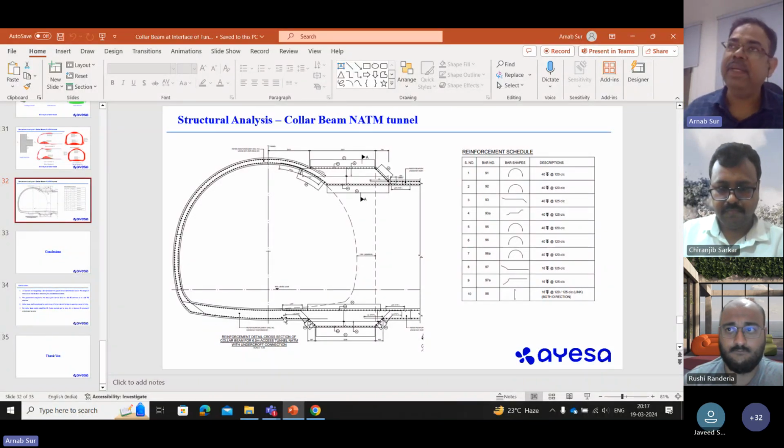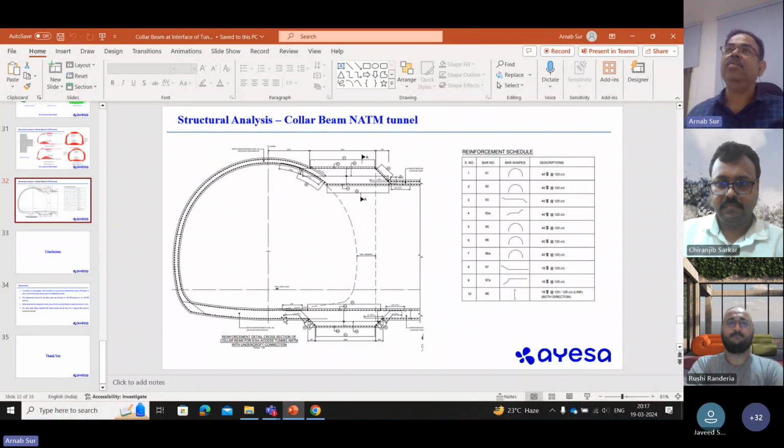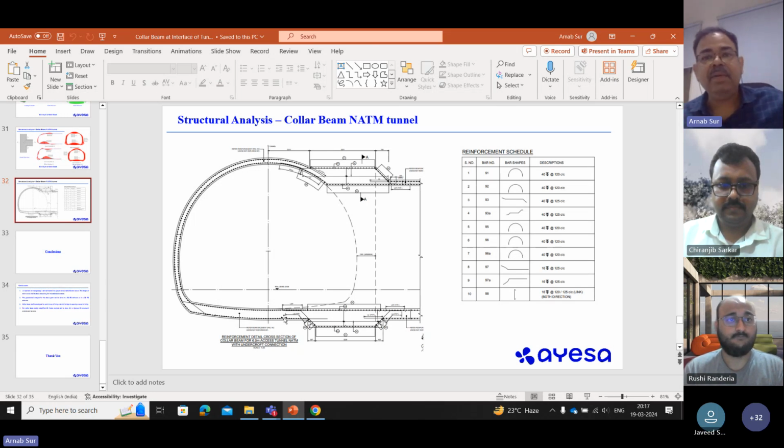We do the complete reinforcement continuity there and we lap everything there. We prefer a staggered lapping there. So there is no reduction in strength at the CJ location. So CJ can be planned based on construction, but again, the minimum number of CJ should be there.